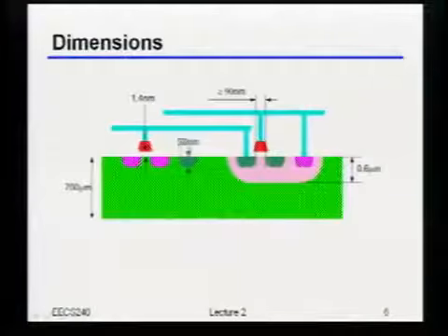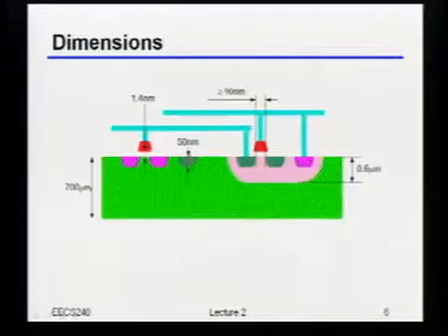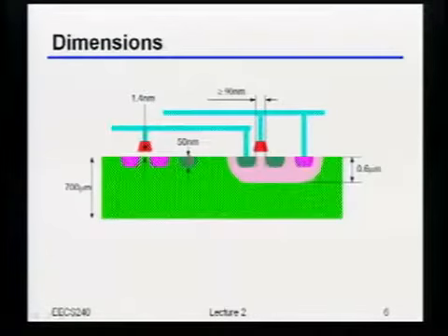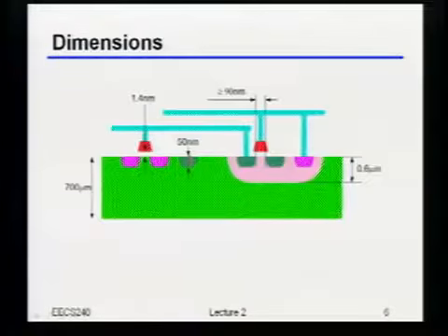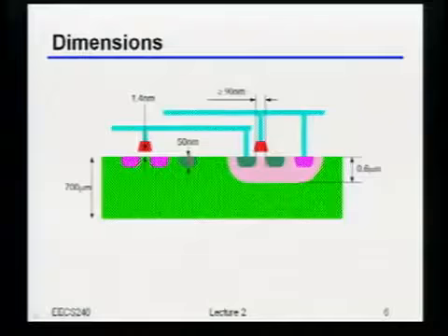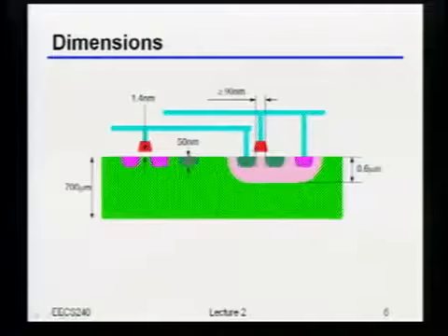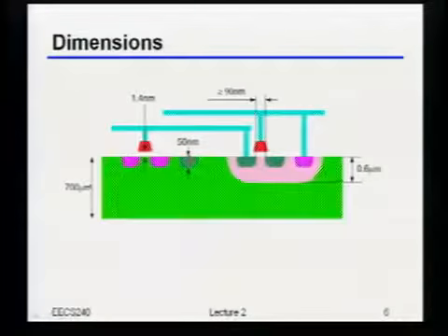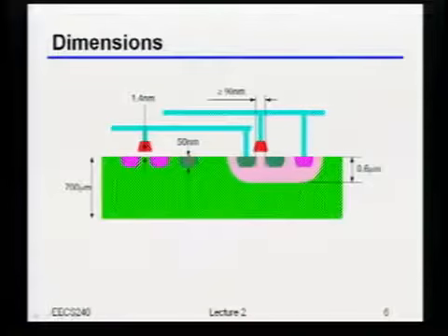Just a couple other things that I wanted to point out here. These thicknesses that I annotated here, obviously, this is just something I made up, but this is fairly common. This is an example of these source drain regions and these contacts. Typically, they're about 50 nanometers or so thick in terms of the diffusion region there. Anybody have an idea why that might be something important that you're going to care about in the context of an analog design?